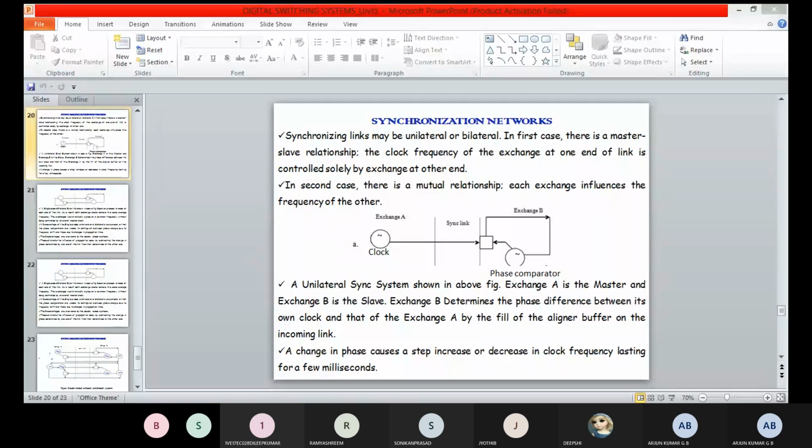One way is to provide a separate switching network for each direction of transmission. This can be avoided by connecting the sending highways for both incoming and outgoing circuits to one side of the switches. Similarly on the receive side, we avoid the extra connection for both incoming and outgoing PCM.